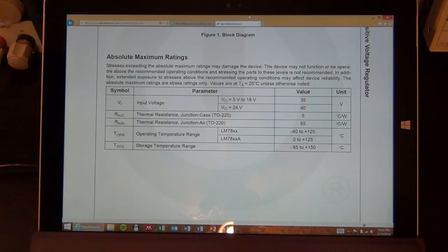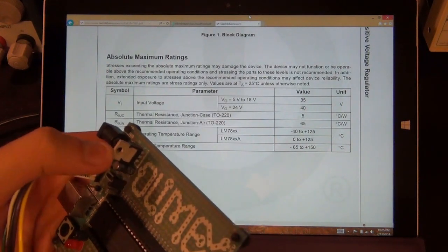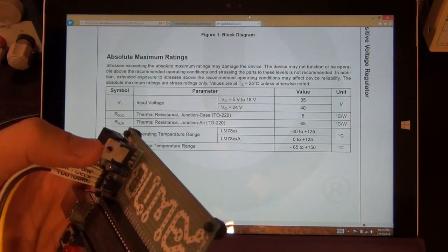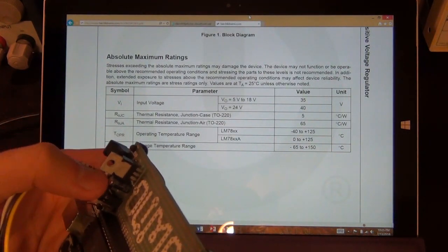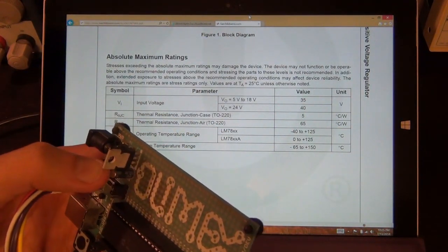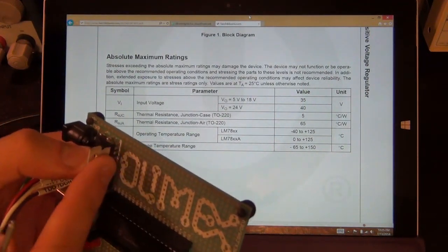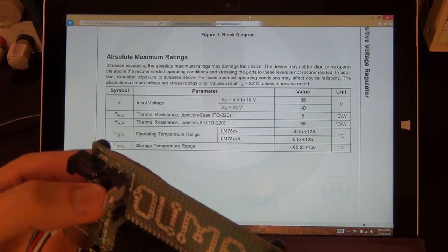It is completely unrealistic to expect this regulator to burn 21 watts. It's just impossible. Its temperature would immediately reach its thermal shutdown, and it will shut down within a very, very short amount of time, less than a second or so, maybe even. It will completely turn off. So powering it through the regulator with a 12 volt supply in is impossible.